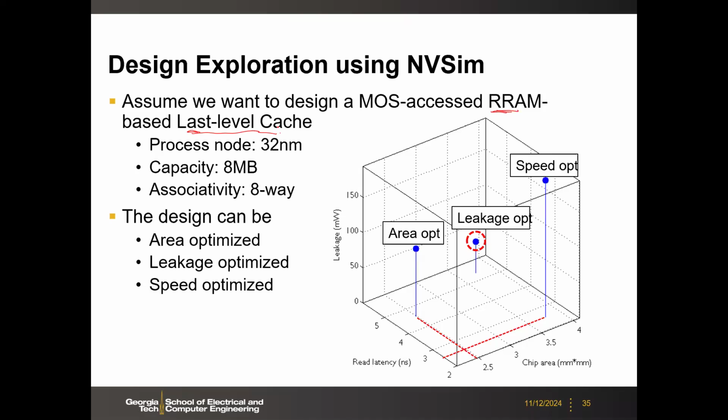Why? Maybe because RRAM is slower than DRAM, like how we saw in the example that SanDisk made, right? And this one is not SanDisk. SanDisk is a special case, but in general, RRAM speed is a few nanoseconds, not 1T1R. Let's say no problem. Okay. So RRAM has an endurance problem. We haven't talked about that, but it's like flash memory. You cannot cycle it many times. Okay, but for last level cache, you rewrite very often. So the endurance will not be enough. Okay.